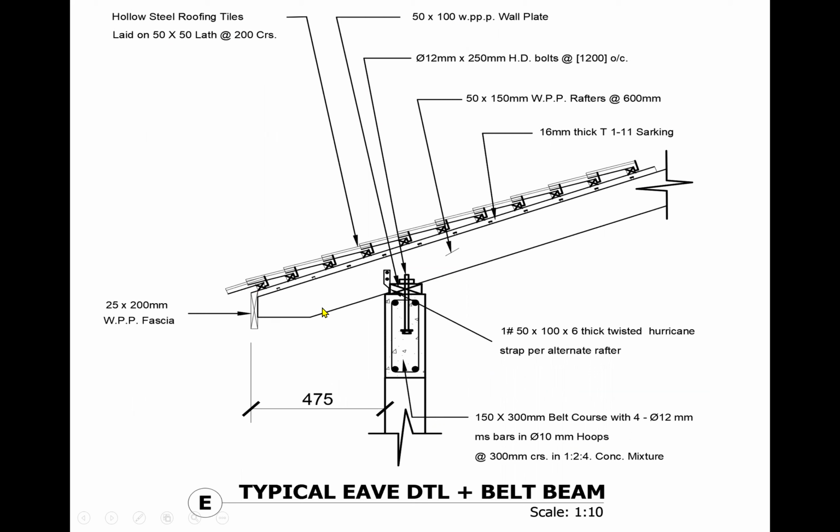So basically, if you are looking at your roof in elevation, you cannot see through the top of the roof. So you would not see this line at all, because that's the underside of the rafter. What you'll be seeing is the top edge of the roof. So what we are going to do is to move this line up to the top edge, where we would basically see. So there's no need for this line. Likewise, we could not see the top of the wall anymore because the roof comes down over it. So it will be hiding that line. So the line I told you just now that we don't need, we're going to erase that.